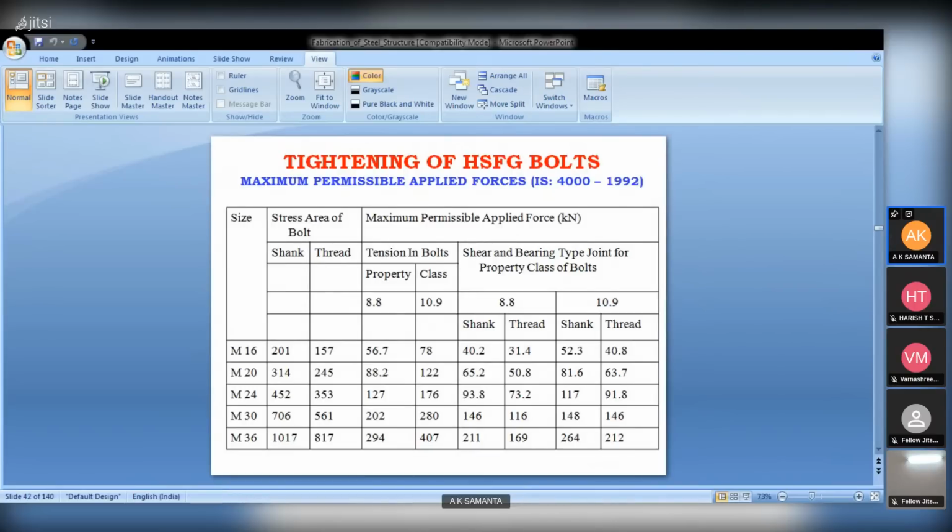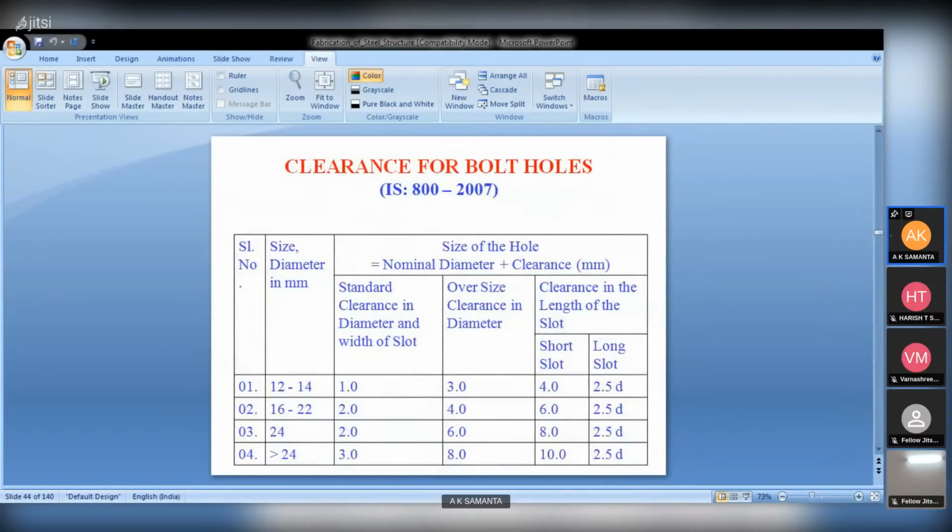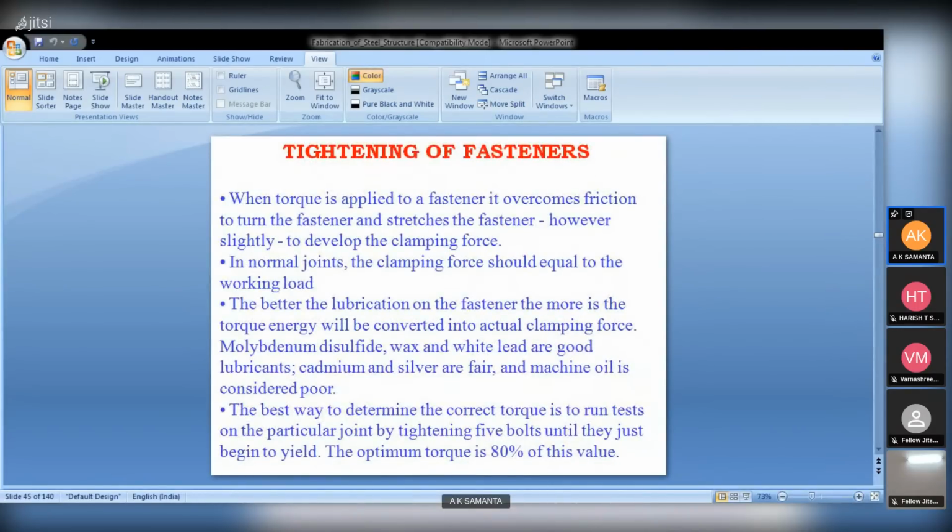Now the difficult thing is that when we are giving the bolt tension, how to measure that it is actually achieved at the site. Though it is theoretical analysis, it is very difficult to practice at the site. Rather, the calculation of the torque and applying it is the best method. Okay, so I am giving you that portion.